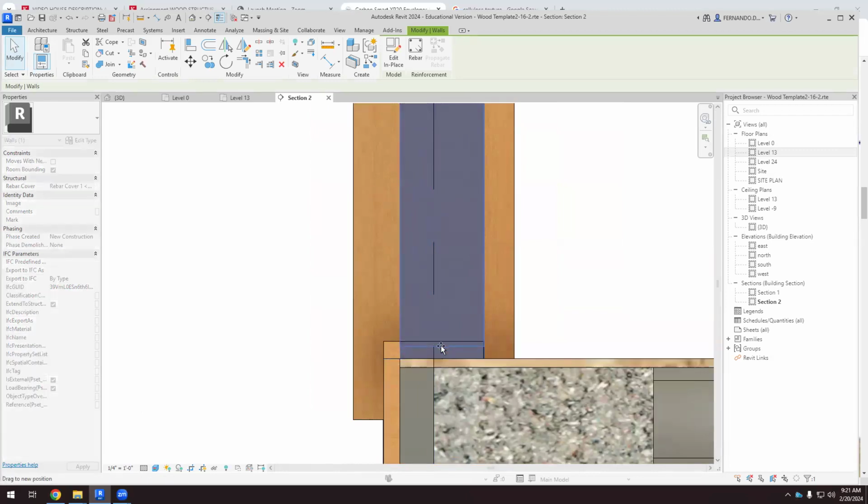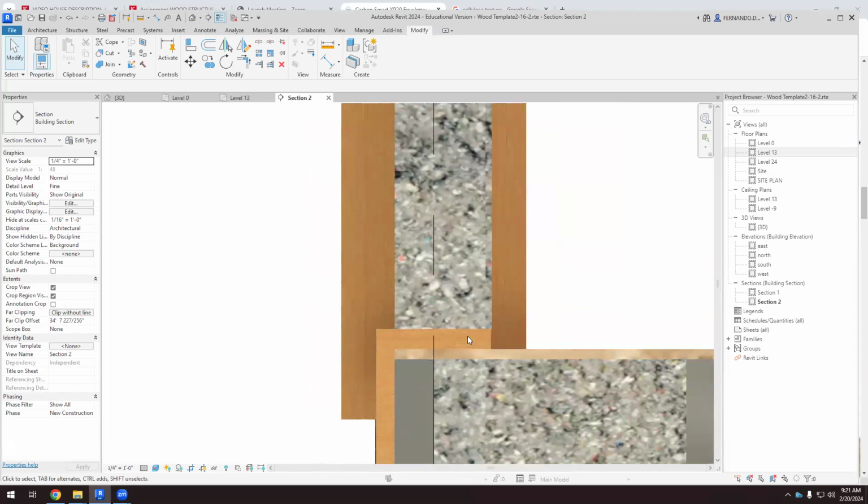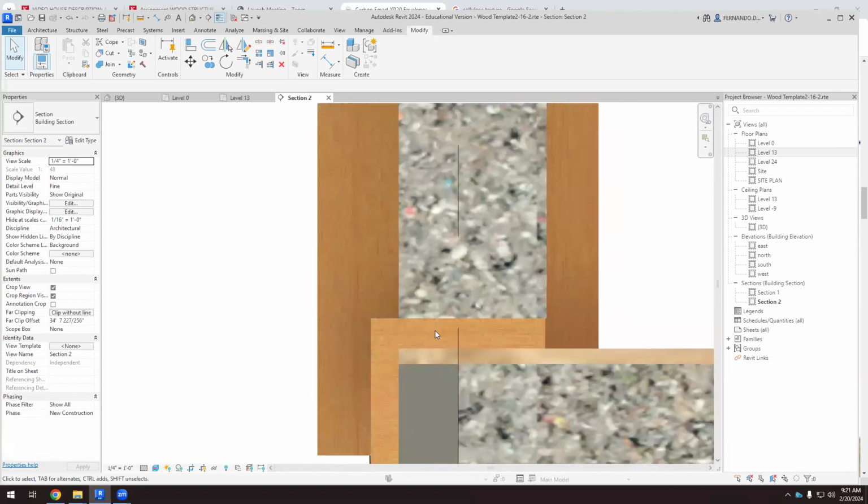No, this has to go up here. Yes. So that's what I mean. Probably there's a thermal bridge here, but it's very difficult. So I can solve this thermal bridge then with the exterior siding, and I'll do that.